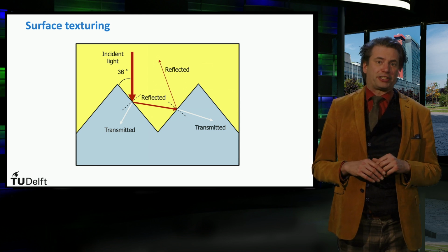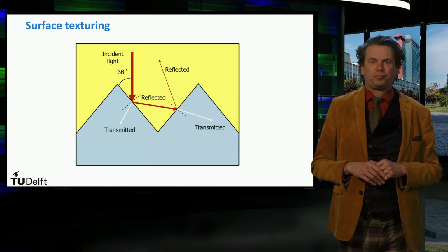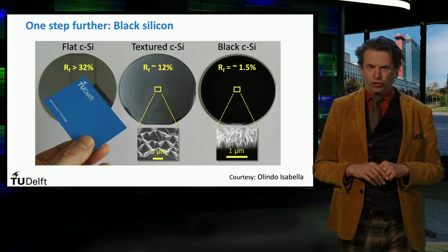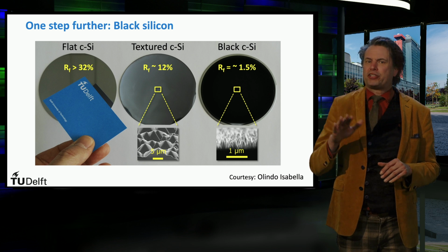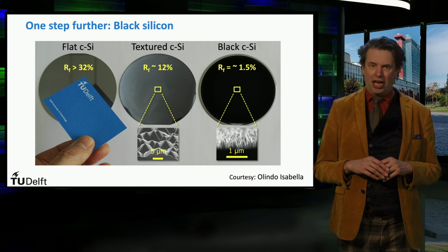The texture on the wafers can be realized with a wet etching approach. Here you can use an interesting property of the 100 surface. This anisotropic etching can be used when etching a crystalline silicon wafer with initial 100 surface orientation, as shown on the left.